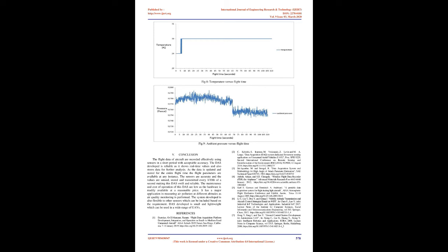The specific location is chosen where the value of the sensor drift is very small. The drift in values is due to vibrations incurred in the aircraft. The transmitted signal will be in the form of a string. This string needs to be split accordingly to obtain the flight data values using LabVIEW.